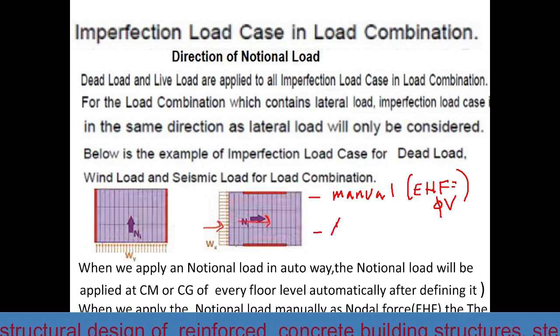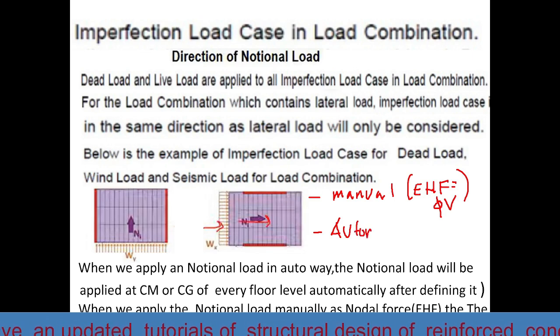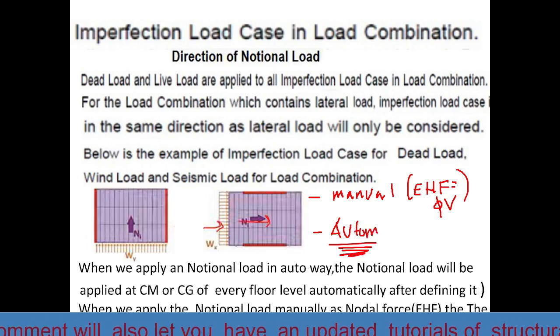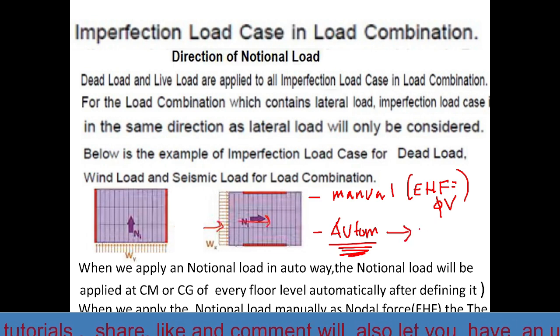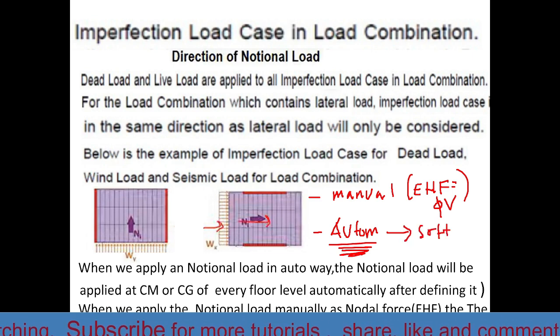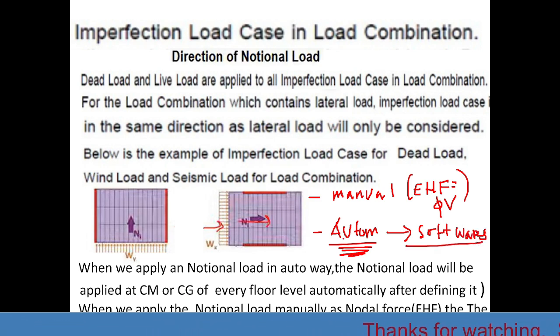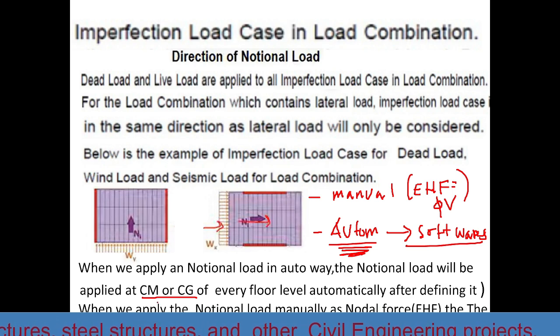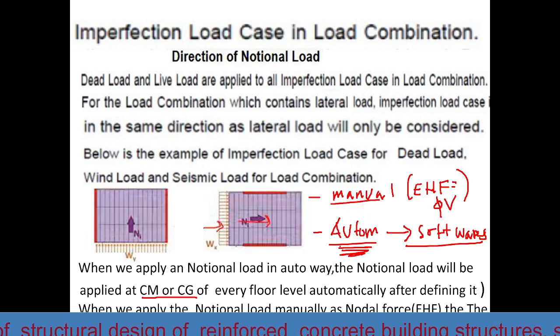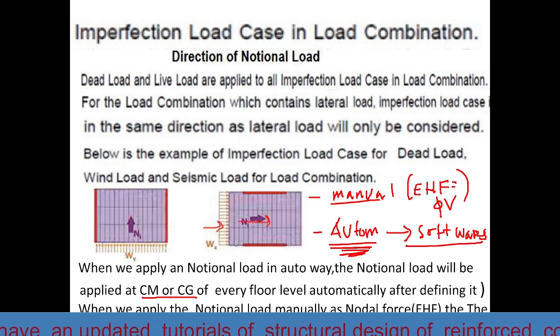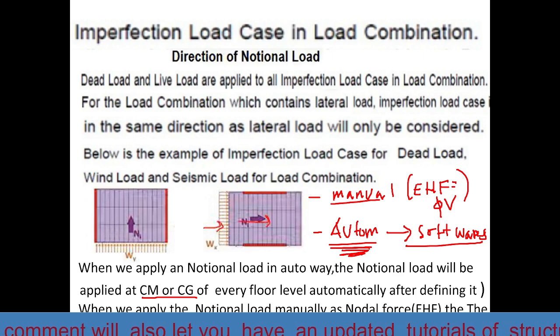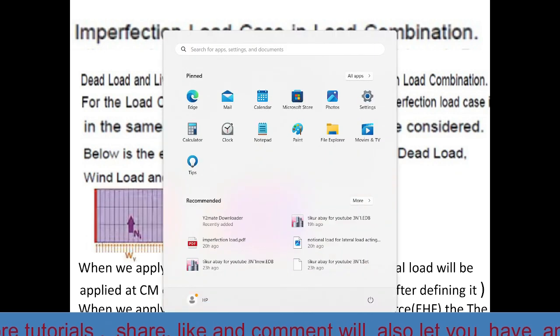Or we can use automatic application using software. In this case, the notional load will be applied at the center of mass or center of gravity of every floor. Now let me show you how to apply the manual and the automatic way in this two-story building.